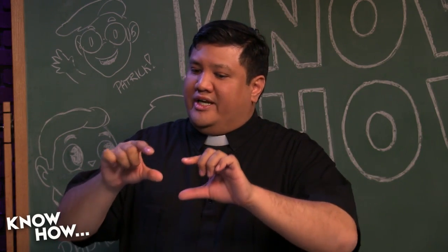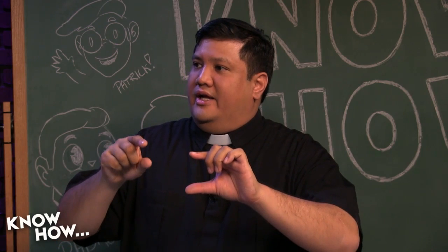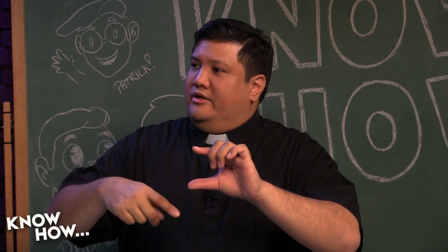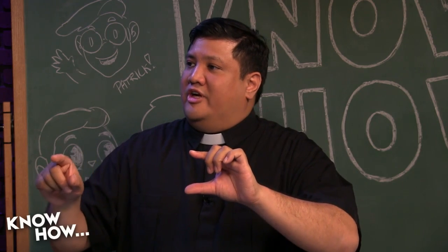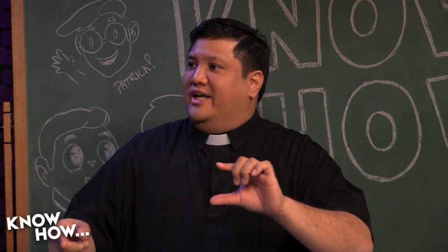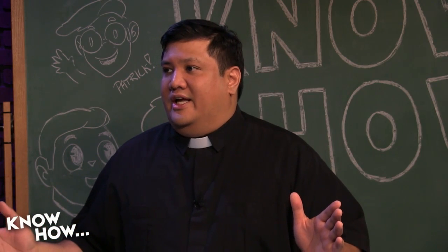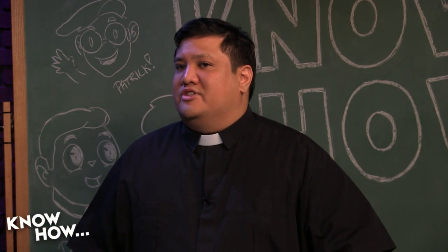So what I would do is, rather than using delay, I would run an internal counter, and I will say, okay, keep running, but when this counter equals a certain number, then do the next thing. So rather than saying wait 2 seconds, it's going to say, what's the time? What's the time? And then, oh, it's the time. Run it. And then run.